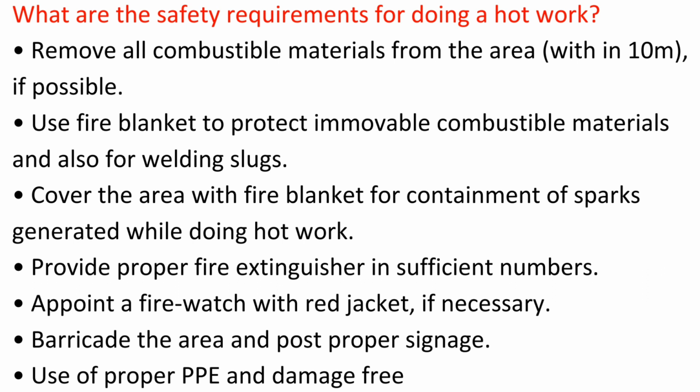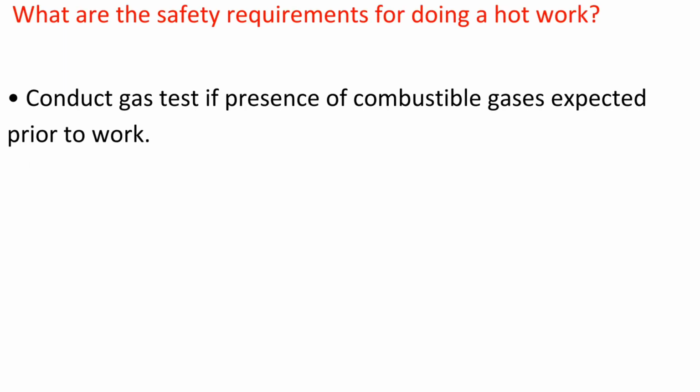Provide proper fire extinguishers in sufficient numbers. Appoint a fire watch with red jacket, if necessary. Barricade the area and post proper signage. Use proper and damage-free PPE. Conduct gas test if presence of combustible gas is expected prior to work.